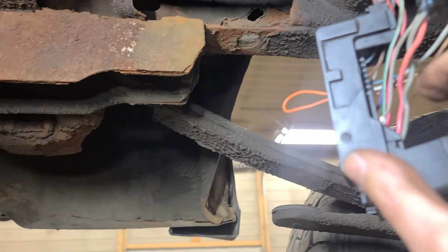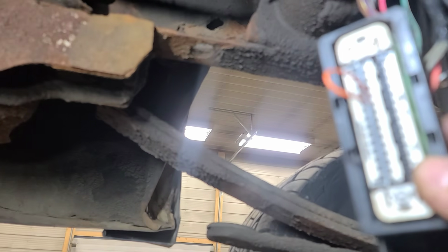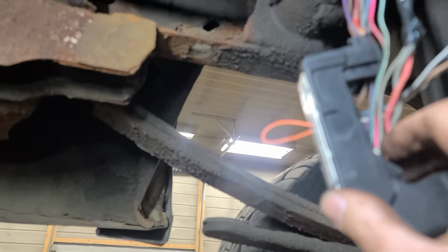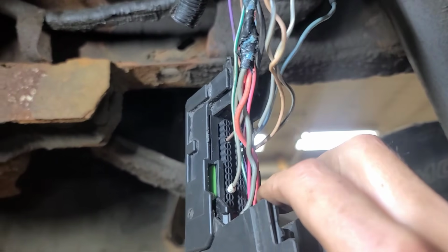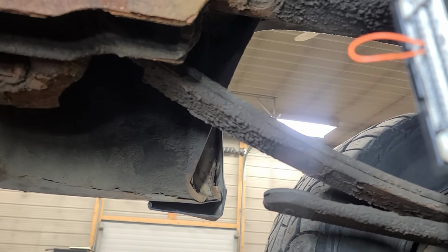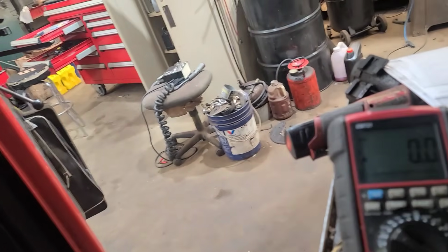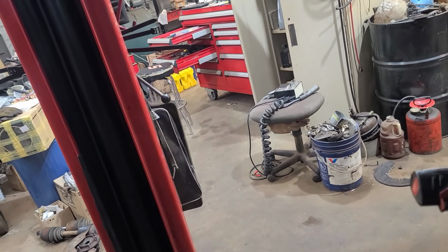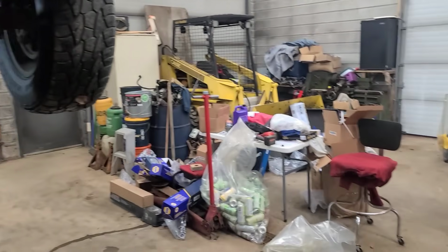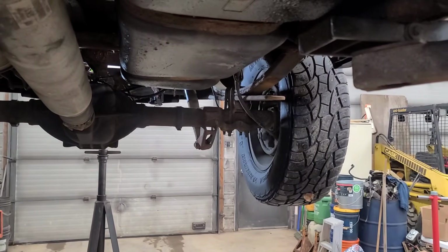So I checked the 6 and 7 on the outside here, and that goes to the terminating resistor. That measured 120, and I've replaced all 4 wires in there, and I've got it shorted between the 2 pins coming into the CAN bus, and my ohm meter shows 0. So if I plug this in, theoretically I should read 120, because the terminating resistor is on the other side of that fuel pump control module.